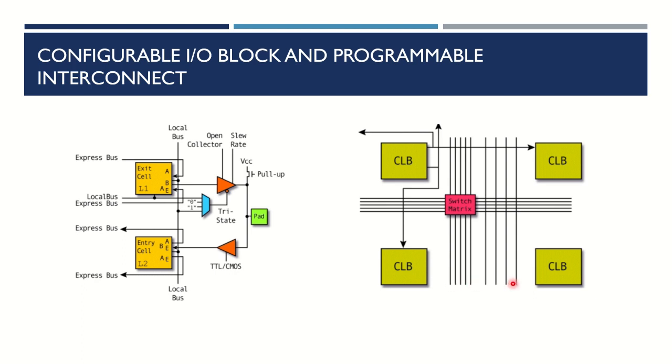These are relatively high speed local connections through metal, but are not as fast as hardwired metal connections. Special long lines, called global clock lines, are specially designed for low impedance and thus for faster propagation times. These are connected to the clock buffers and to each clock element in each CLB.